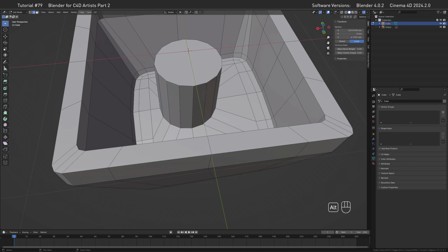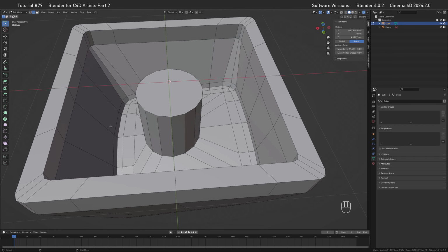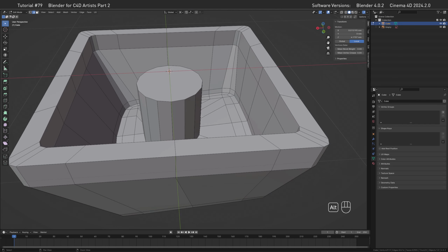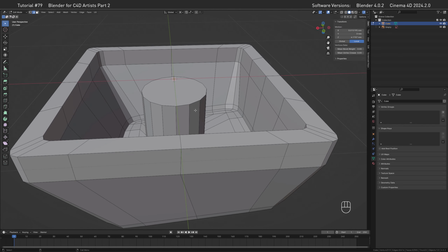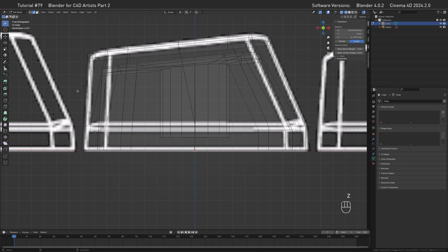So I want the connections to all sit flush within one level, so let's do this by cutting across the whole keycap. There might be multiple ways. The way I did it is go to side view and use the cutter tool again. To see a little bit more what we are doing, let's go to wireframe mode here. And I want to cut across here, roughly.